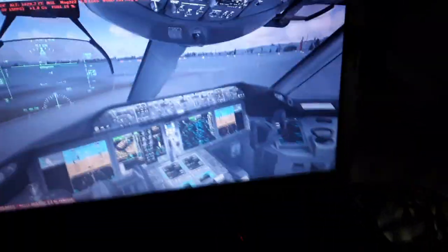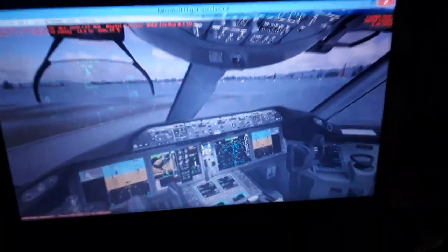So we're gonna see now the flight management computer. I will input all the data of this aircraft for this flight, and it includes the takeoff gross weight, the empty weight, the passenger load, the cargo load, and the fuel on board. The fuel is stored in the left and right wings and the center tank. We have 30% fuel in the left and right wing tanks and 10% in the center tank.